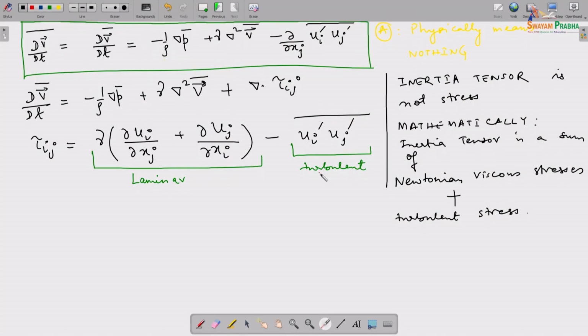So, there is this differential movement between layers of the fluid. We are talking about turbulence, where is the layer? There is no layer here. At the same time, there is a certain viscosity element which is involved, right. So, there is the shear that we are talking about. So, we understand what tau is. Now, in that context, using this shear, we get these two terms here, and using the gradient of the shear is what we are supposed to get back this, and you should cross check that. So, when I write it in this fashion, then I see that this can be looked at as a laminar part and a turbulent part.